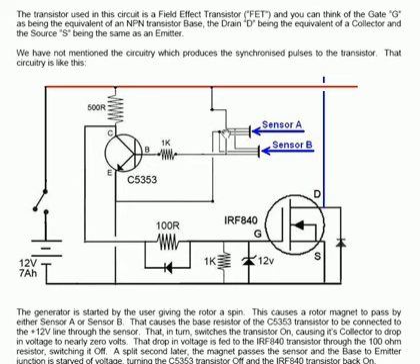so the sensors are both connected directly across the plus and the minus of the battery, and when the magnet passes by, the resistance of the sensors changes from very high to very low. That effectively connects the plus line of the battery through a 1K resistor to the base of this particular transistor.